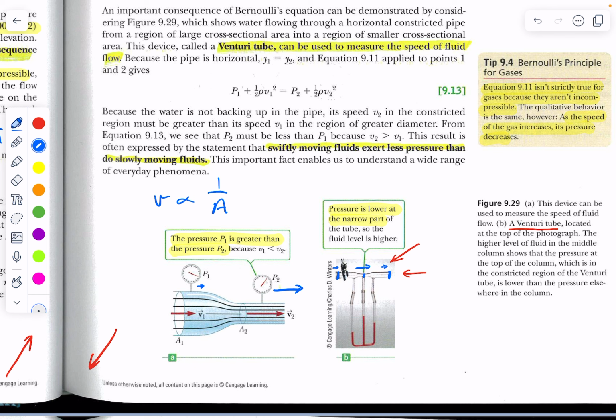And you can see that you get these differences in pressure. We can also say, therefore, that your pressure is going to be inversely proportional to the speed. And let's make sure we get the tail on that v. So you can see that where the speed is the greatest, we have the least pressure. So I'm going to put a circle, like a low pressure system. We have our lowest pressure there, and so the liquid is going to come up in the direction of where the pressure is lowest. Where the speed is slower, we have the greater pressure. So we have a high pressure system there, and therefore, since the pressure is greatest there, acting down, these heights are the least. Over here, you can see it again. We have high pressure where the speed is lowest, and we have a lower pressure, the gauge is farther counterclockwise, where the speed is the greatest.